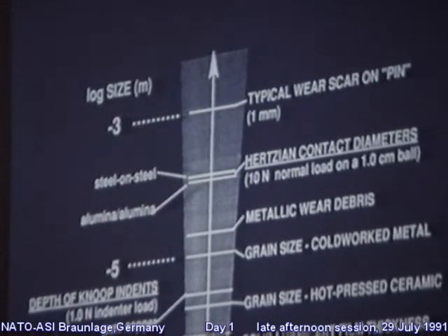And then if we go slightly higher, we get to the size of mild wear debris, and Charlie Yust at Oak Ridge National Laboratory has spent some time in a transmission electron microscope looking at the sizes of wear debris for ceramics, and we see 80 to 100 nanometer diameter particles, which are typical size. Then we go up to surface roughness, perhaps 0.02 to 0.04 microns for a polished surface, thereabouts.